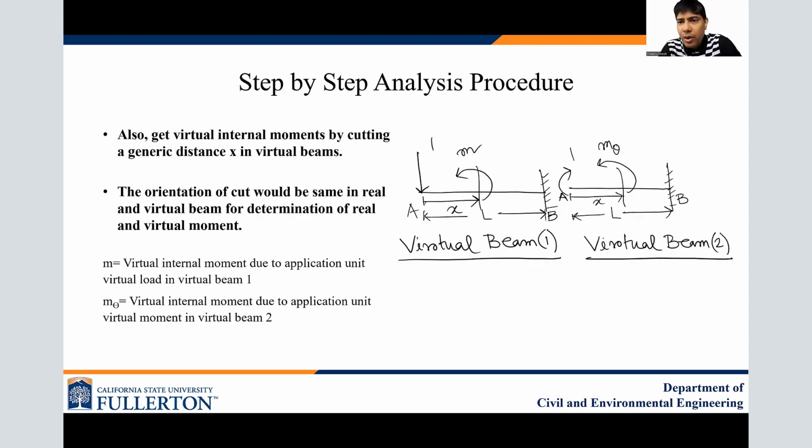For slope, it is m sub theta. For vertical deflection, it is lowercase m. So both of them are virtual moments, internal moments, one due to application of unit load, the other due to application of unit virtual moment.